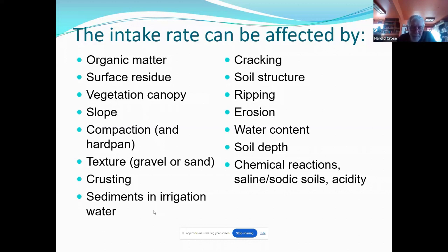We also pick up saline soils where there's poor subsurface drainage. And so that becomes a real problem. You say, well, why is that? Well, if you've got a salty field, a saline soil, you're not going to be growing beans on it for sure. There are certain crops that really can't remove the water from the soil if there's a saline condition. It's just chemically impossible for them to do that.